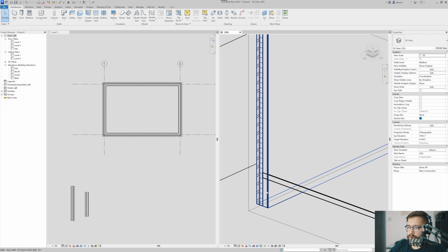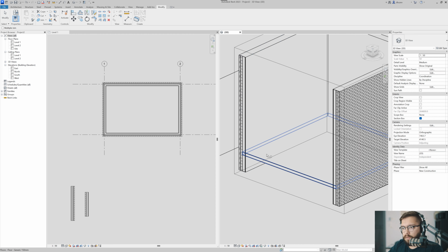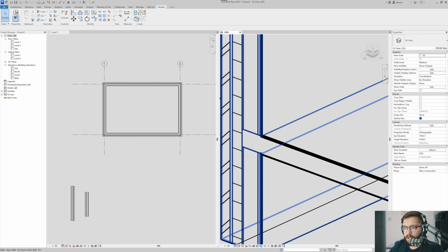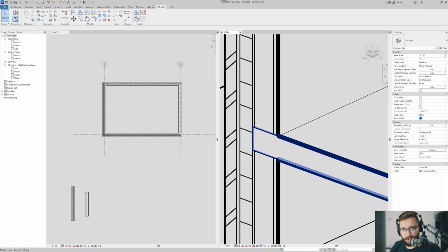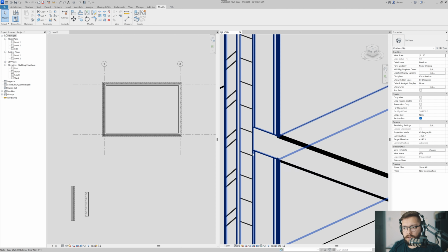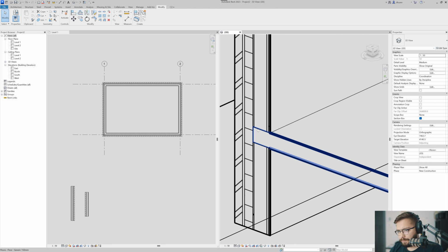And even if I go as far as to, let's say, join this geometry, because this is also something you can do in Revit, you can join stuff. If I join this geometry, you would see that it would cut right through it. Remember when I told you that Revit is a way to hyper-categorize things? Well, it's also to create hierarchies of importance between elements. The floor is always more important than the wall. So this is why the structure of the floor, which by the way, the sandwich of the floor behaves in the exact same manner that the wall would behave, will take kind of dominance over the wall, and the wall would give way when you do the join.